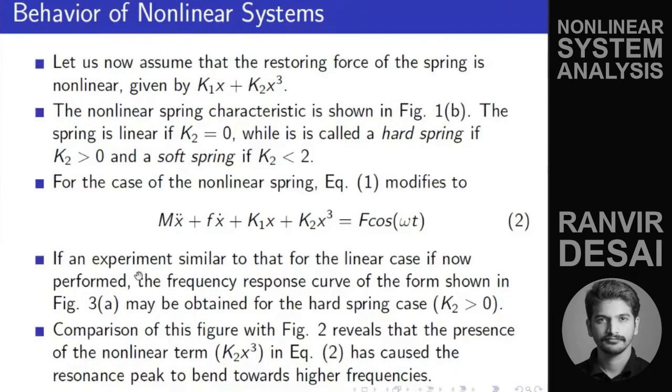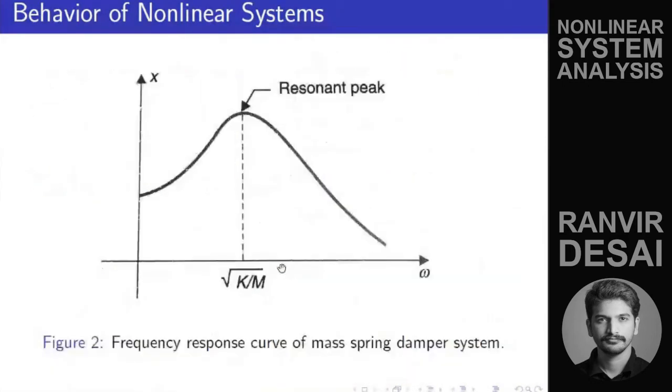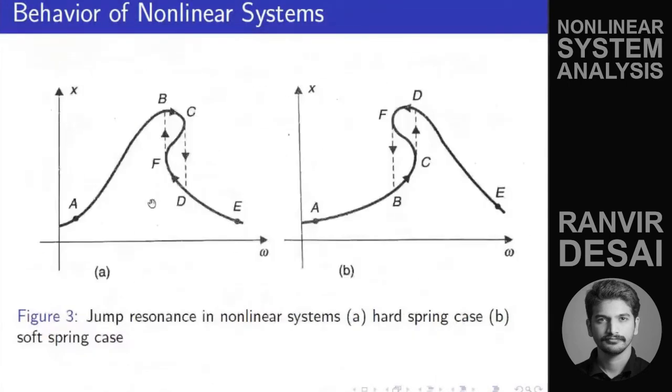If an experiment similar to the linear case is now performed to find the frequency response curve, it will exhibit these graphs, for hard spring and soft spring.